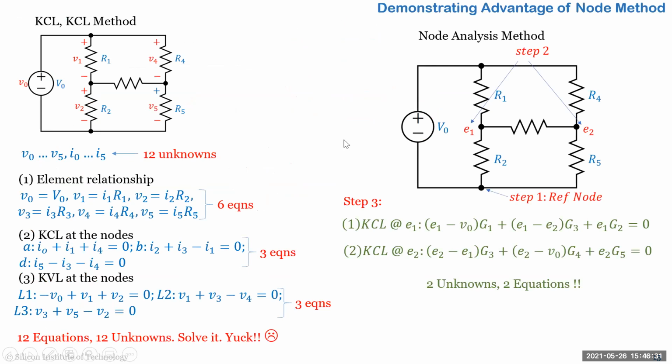All right. So here I again show the difference between using the KCL KVL method, the brute force method, and using node analysis, and why doing hand calculation using node analysis is a more efficient way. If you take this circuit here, for example, a bridge circuit, you can see that you have, I mean, 5 branches, 1, 2, 3, 4, 5 nodes, right? No, yeah, sorry, 6 branches, 6 nodes here. So you have a total of 12 unknowns.